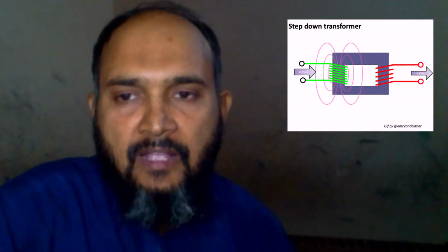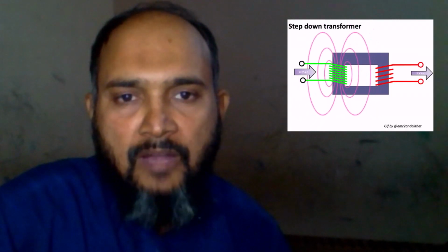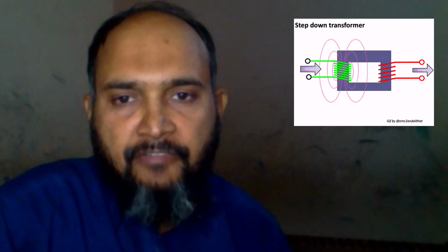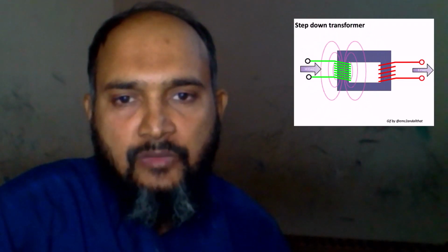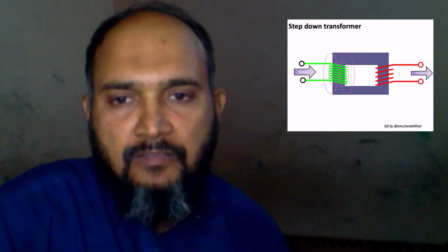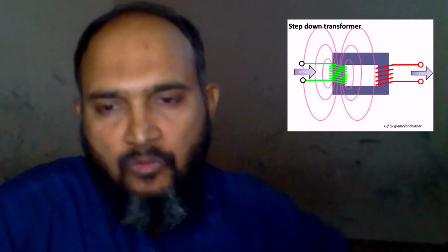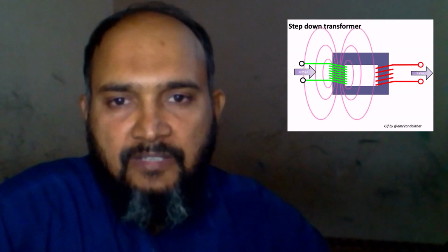Indeed there is. There is the effect of electromagnetism known as mutual induction, where two or more coils of wire are placed so that the changing magnetic field created by one induces a voltage in the other. If we have two mutually inductive coils and we energize one coil with AC, we will create an AC voltage in the other coil. When used as such, this device is known as a transformer.